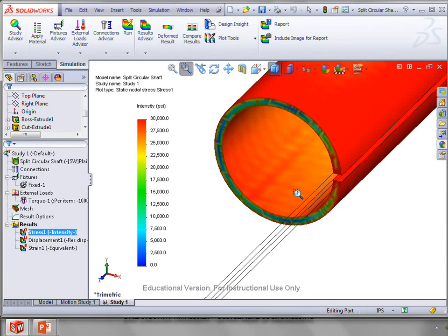So if you want to think of it this way, almost think of it like water in a pipe, that the shear stresses can't flow all the way around like this, so they have to kind of turn around and come back. And so the distance that goes into your calculation of a moment that's necessary to generate the amount of torque, the distance between the opposing shear stresses, is very, very small here, as opposed to if this was continuous all the way around.